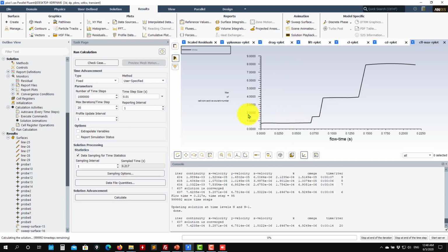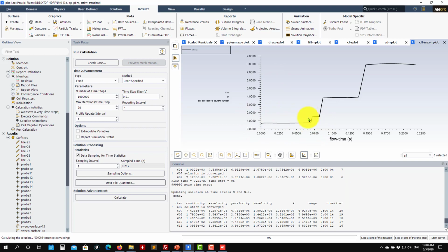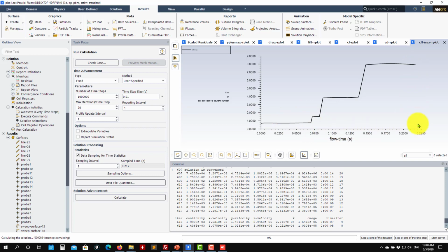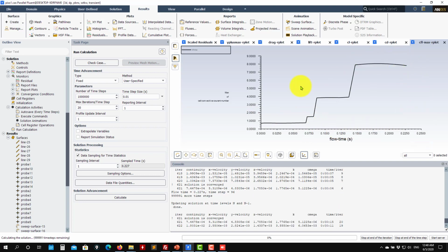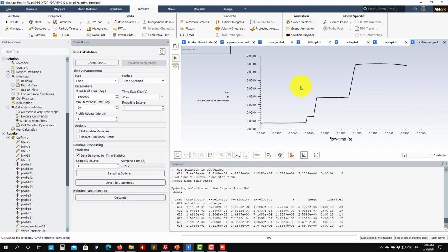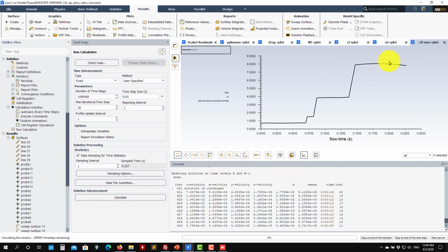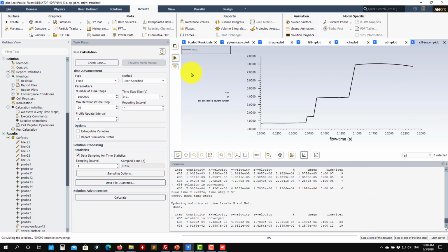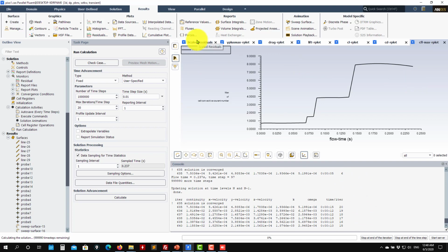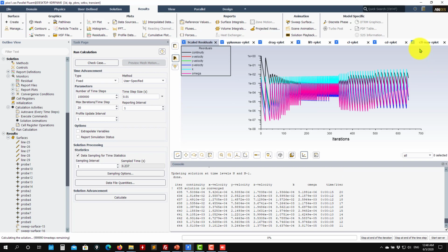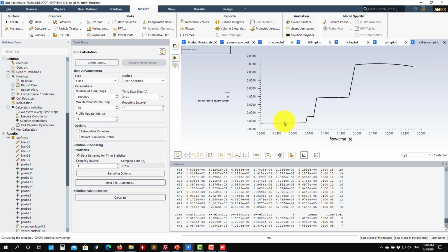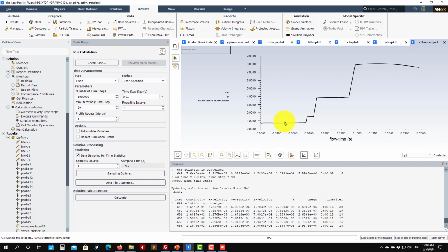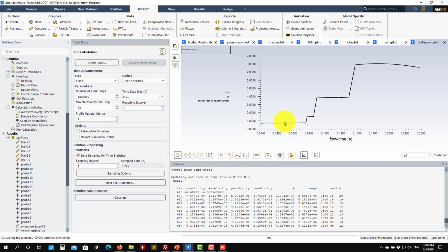So see, you start to run that one, you will see that to reach this time here, it took probably like 5 minutes. To reach this time here now, it was really fast. Okay, you see that with larger times you will advance in physical time much faster. And see that we're kind of capturing some unsteadiness there. It's taking about 14 iterations, so it will be a compromise. Okay, so initially here was 4 iterations, and now it will be 14, but you are running at a time step that is 10 times higher. Okay, so yeah, it's a compromise.